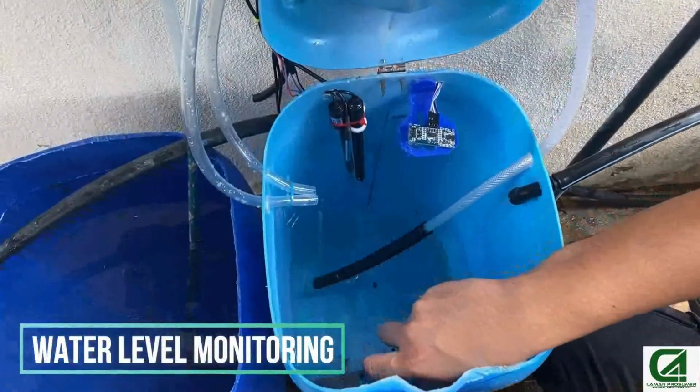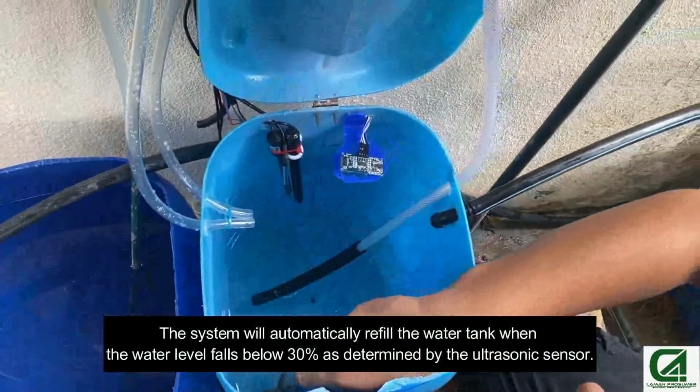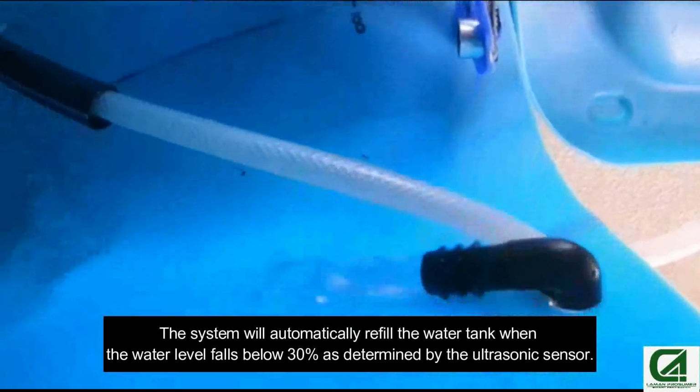Water level monitoring. The system will automatically refill the water tank when the water level falls below 30%. It is determined by the ultrasonic sensor and it will fill the water tank until 100% of the tank.